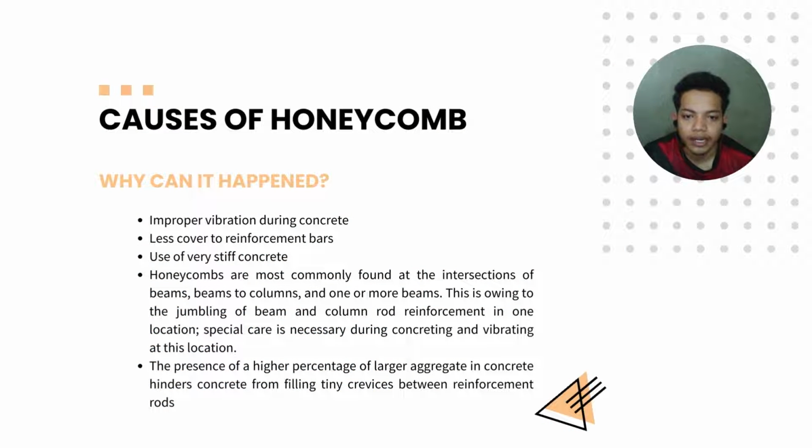Causes of honeycomb. Do you know why it can happen? Actually, honeycomb is because of improper vibration during concreting, less cover to reinforcement bars, and use of very stiff concrete. Honeycombs are most commonly found at the intersection of beams, beams to columns, and one or more beams.